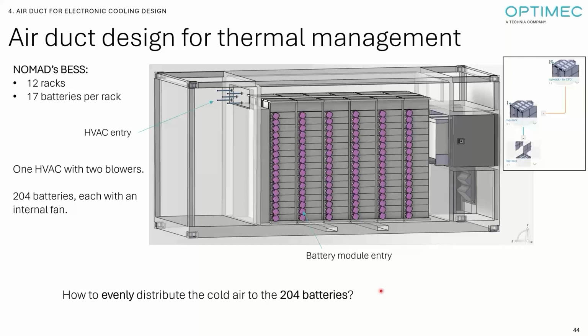But there is a big challenge here. There is the weight. So we do a lot of structural simulation, of course, the lifting crane, lifting forklift. We do transportation load cases from standard. We do seismic simulation with linear dynamics. We even do sometimes blast simulation, simulating a thermal runaway and the ignition of gases inside to make sure the container is strong enough to contain the blast.